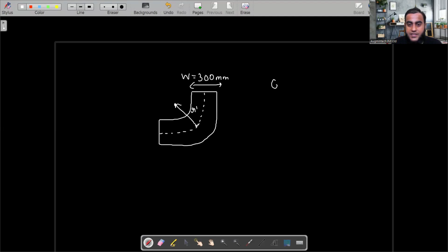So to calculate the center radius, R dash, here, you have to use the formula. First of all, just calculate this value from this point to this capital R value. Okay, plus width of duct divided by 2. So to calculate the capital R value, simple. What is your width? Same that you have to consider. Means capital R, in this case, the capital R value is 300 because our width of duct is 300. And then W by 2, 300 by 2.